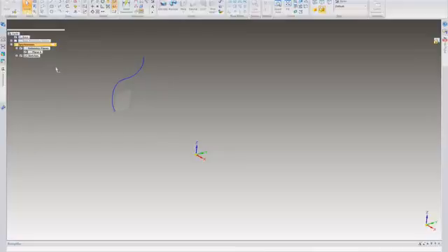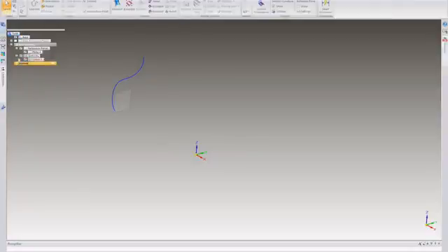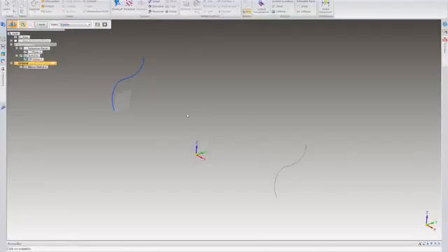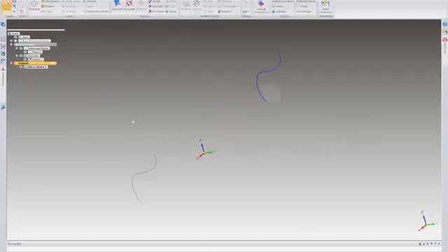All right, so to get what I need, I'm actually going to take this into an ordered environment. I'm going to go ahead and create a couple different shapes and sweep through space. All right, so what I'm going to do is quickly switch over to transition to ordered. The reason I do this is the sketches are controlled differently in the synchronous style as they are in the ordered environment. So I'm going to go ahead and mirror that sketch over, so I'm copying and mirroring a sketch from the synchronous to the ordered environment.